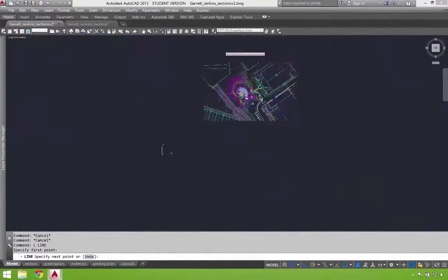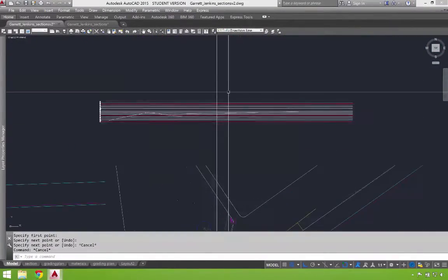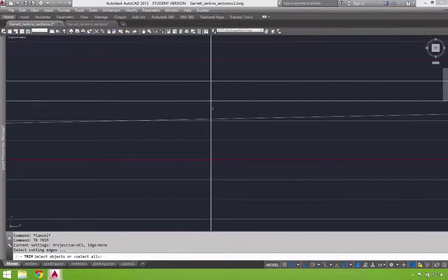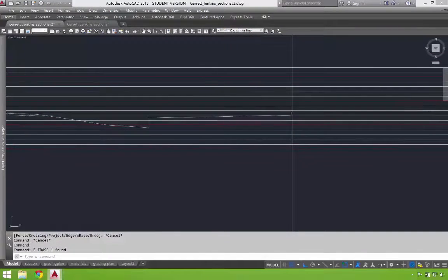It will stop right at this wall. I'll pull this contour up and trim my 2% slope at that point. So I know that this is that 2% slope across the stage. Now that's one way to create that.